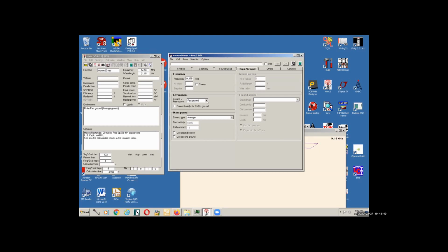He used something called fast ground in this particular one, but if I really want to look at this, I can do real ground, and I can pick either average, or they have different defaults you can pick. Here, as you can see, fresh water, all kinds of stuff, marshy flatland. But I'm going to put our real values in here. So I put user specified, and this comes up with 0.05, and ours isn't quite that good. Ours is more like 0.02. That's good for that.